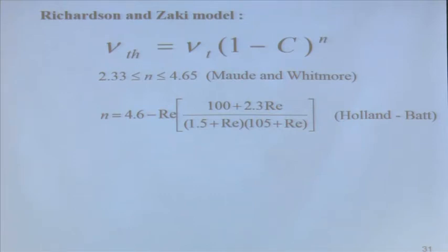That system is different from our mineral processing system, where I have got a variation of size and a variation of density. So, it is called polydisperse and polydense suspensions in our case. Okay. So, anyway, when I do not have any other better method, many times we are forced to use it, but be careful that it is not the ideal model. This model was not developed to deal with polydisperse and polydense suspensions.